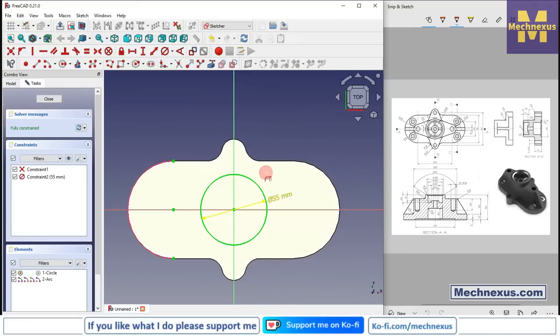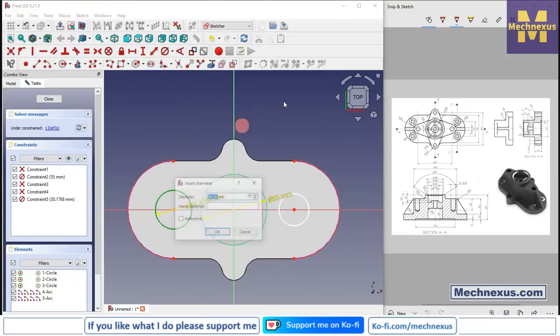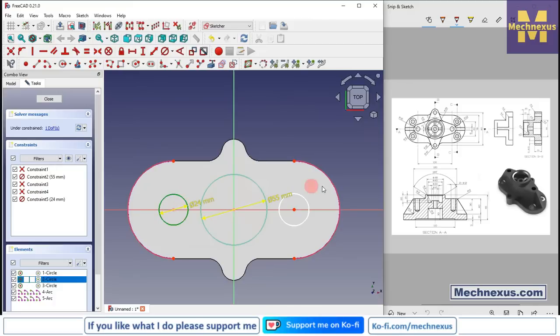So we will select this and this, so we can get here center points. And here we will create a circle, and this is of a diameter 24, and select this and make it equal.